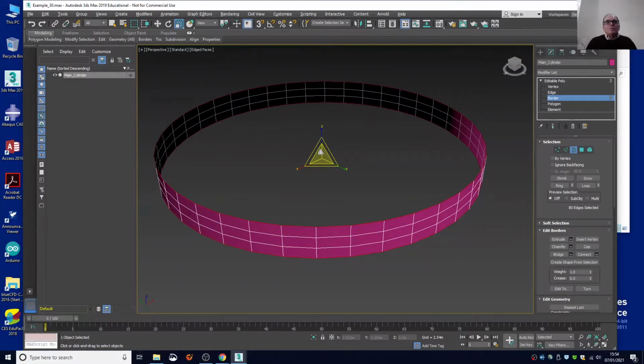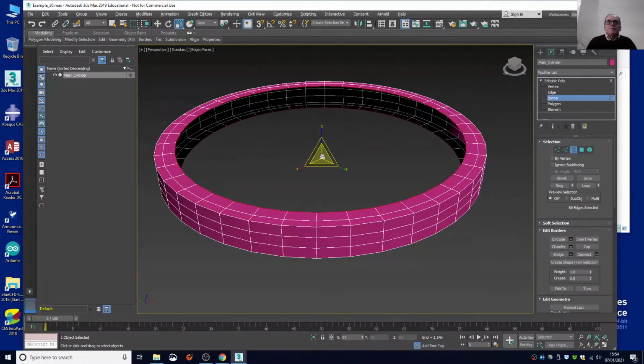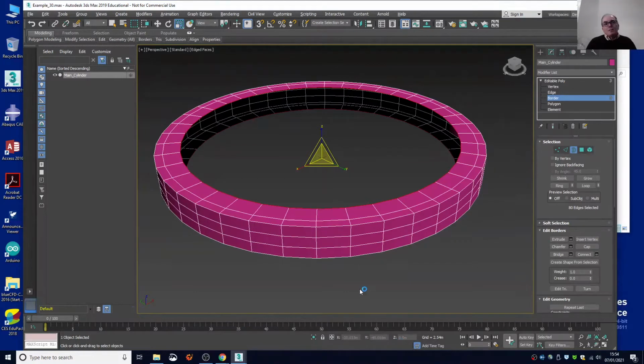So we're going to shift down until we get 95 here, then we release the click, and then we're going to carry on going down with the shift button still on. We only release the click of the mouse button, and you're going to go to 90. So we've done 95, and now we do 90, and we release the click, and we release the shift. Okay, so we have these 2 edges added to our object, and we've checked at the bottom in these 3 boxes that it went down to 95 and then down to 90.